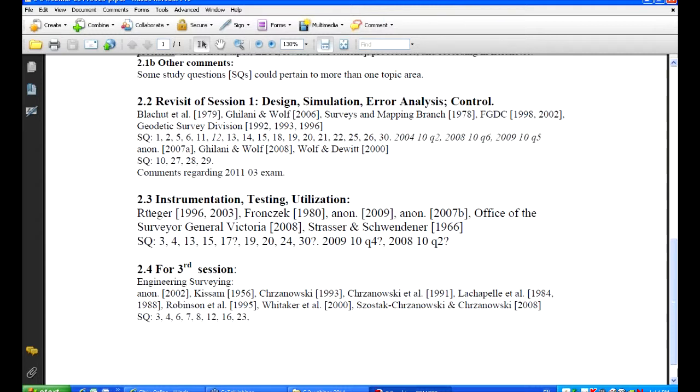There are ways of determining it. If you look in some of the plain surveying textbooks, they say, well, if you take 3 points in a line, do the two intermediate distances and the overall distance, you can calculate what the additive constant is. The problem with that is that it's a unique determination, and there's no way of statistically checking what's going on.